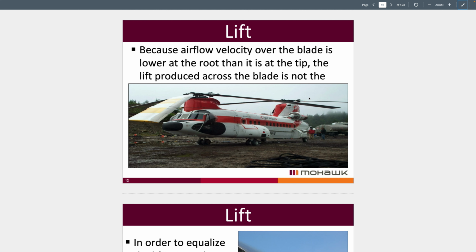Another way a blade is designed to compensate for that difference is by using a thinner or smaller blade section at the tip. So the summary for this would be, because at the very tip of the rotor blade we're going to have very high velocity, this will cause a tendency to create much more lift on the outermost portion of the disc, sometimes even risking overspeed.